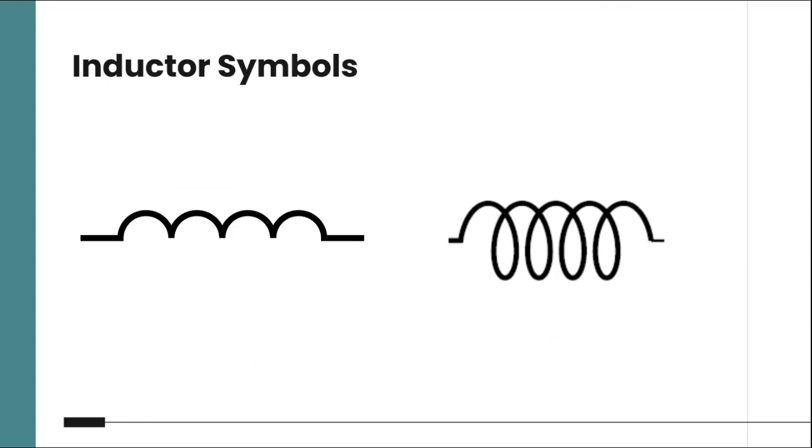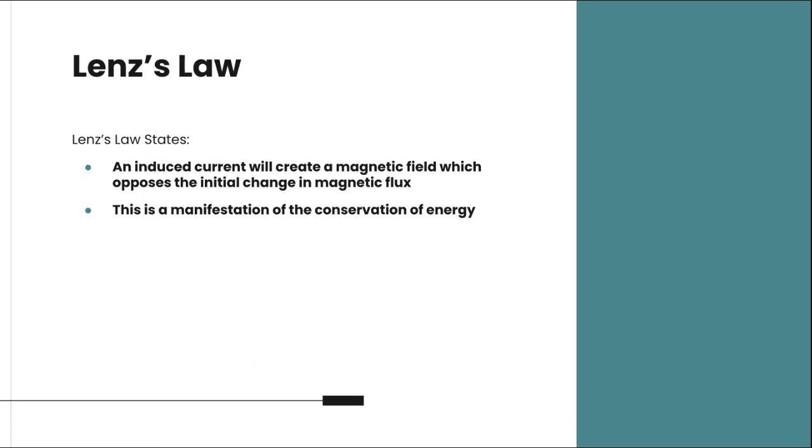In simple terms, inductors produce an electromagnetic field which opposes changes in current flowing through them. This is due to the change in current causing a change in flux, in turn resulting in an opposing EMF produced by the coil as per Lenz's law. As such, when current is increasing through the coil, also known as the charging phase, an EMF which opposes the current will be induced. This property is referred to as inductance, represented by the letter L and measured with an SI unit of henries. The greater the inductance, the more energy can be stored by the inductor.